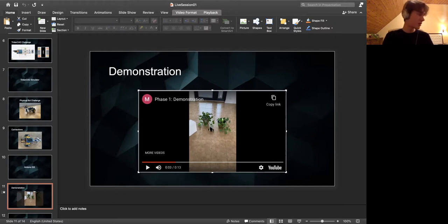For example, they might find it difficult to stop at plants, they might find it difficult to stop at cloth, and so on and so forth. So ultrasonic sensors are only useful if we want to measure the distance from quite structured objects.